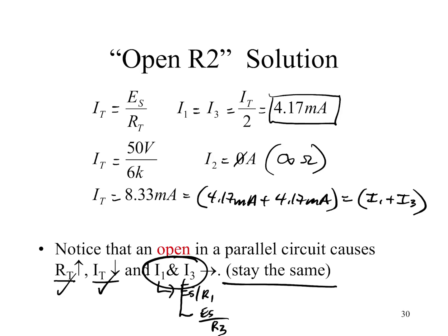And this is how we have independent load operation of your loads within your home, because they're connected in a parallel arrangement. If any one of the loads is broken, disabled, open, or even a switch turned off for that load, the remaining loads within your home still have the source voltage and are still doing the same amount of work and dissipating the same amount of power that they always did. They were independent and unaffected by another load within the purely parallel circuit.